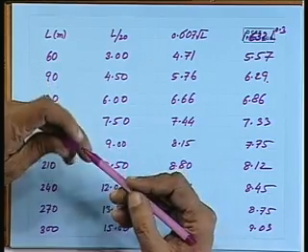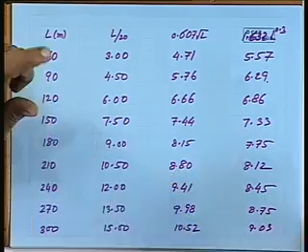Now, this comes from sheer experience, I suppose, and from the statistics that over the past record one can find out what type of wave is occurring in the sea most of the time. What is the probability of a particular vessel encountering a wave of its own length? That is another figure. And then if it is encountering a wave of its own length, what is the height of that? Now, some oceanographic data is available, not complete, but something is available for certain seas, and for those seas one can analyze the data and categorize it.